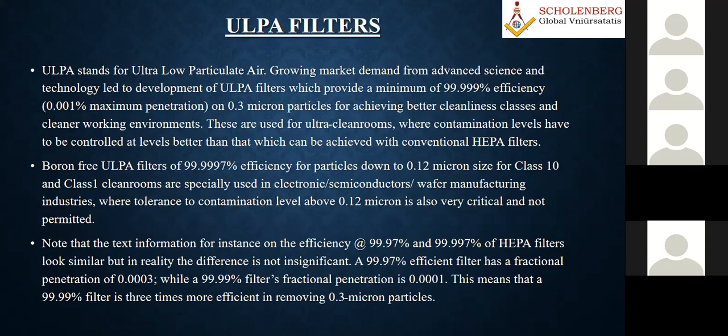And now come to ULPA filters. It stands for Ultra Low Particulate Air, from the name itself, with growing market demand from advanced science. And you have nanotechnology nowadays. Manufacturing technology is also improving. And so all this gives 99.999% efficiency. It allows only 0.001% maximum penetration. But again, it involves money.